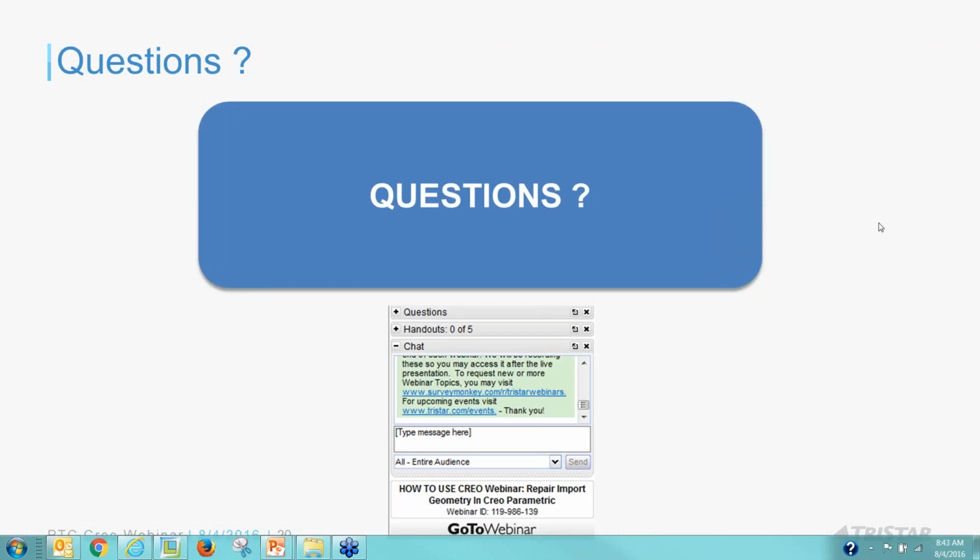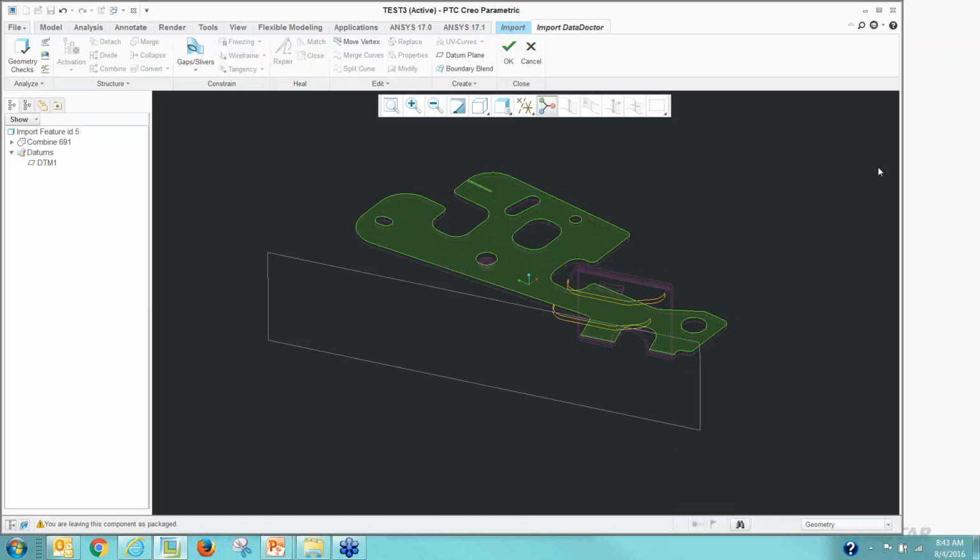With very complex plastic parts, how can we reduce the size or complexity of the part? That's a good question. Now the file size, as you know, is very much dependent on the geometry itself, how detailed the geometry is. So what you could do is use a remove command. You're asking about removing vents, holes, grids, ribs. Is there an easy way? Yeah, there is a remove tool in Creo. I'm not sure if you have tried it. There is under the editing tab, let me just go back here.